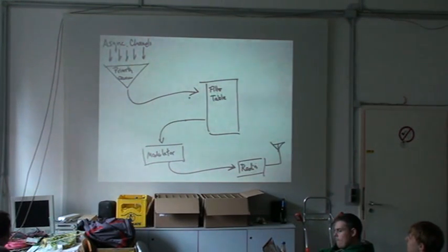Because again, we know that down in the modem, the filler table is going to keep playing that pattern of dummy bursts over and over and over. We don't have to deal with it anymore. Now, if we were really clever and really concerned about computational efficiency, we would make the filler table big enough to carry an entire cycle of system information messages. And then our beacon channel generator wouldn't have to send system information messages either. All we'd have to send anymore is just the sync channel, just to keep the frame numbers rolling.